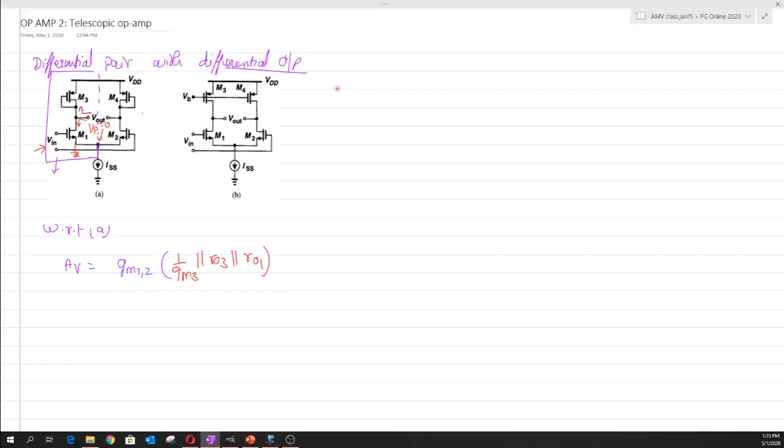This is with respect to circuit B, and again, since the circuit is symmetric, one could draw a line of symmetry across it, and the node at this particular point is equal to 0 when we apply an anti-symmetrical input, due to which one could analyze only half of the circuit.